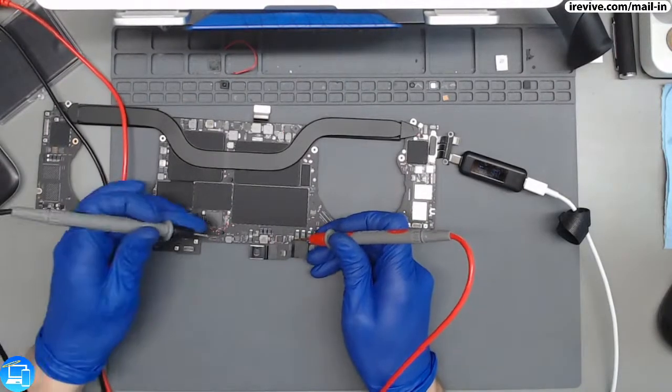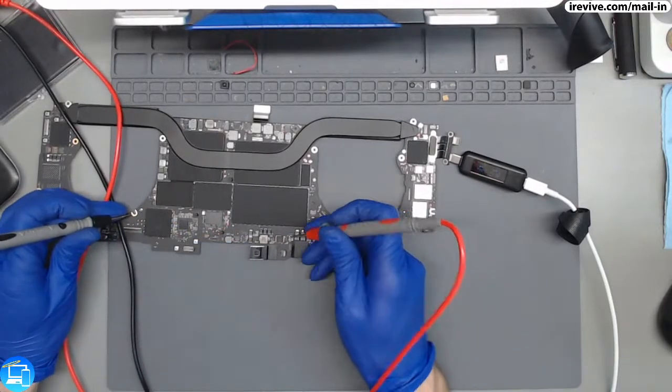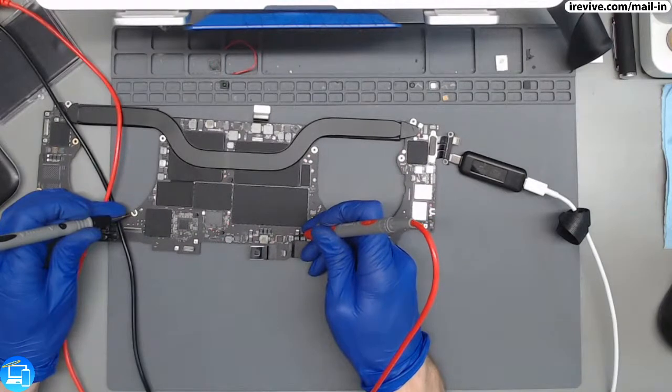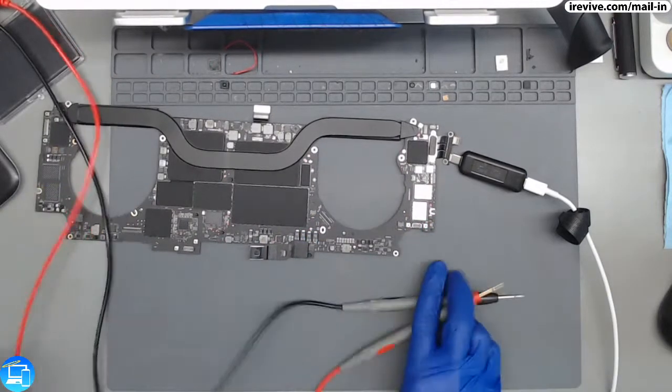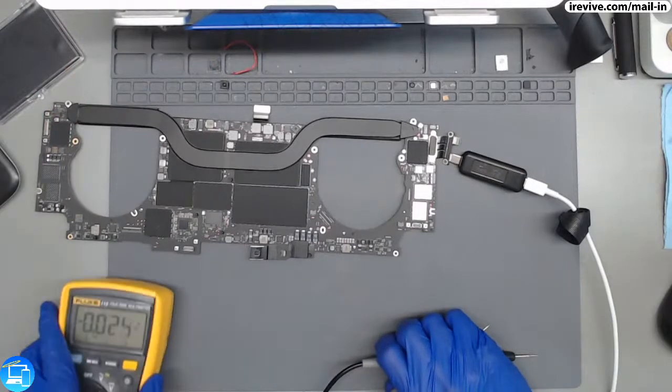Alright, so it's going to be about right here, specifically, are our fuses for our PP bus. And measuring with our multimeter, we are getting 12.61. That sounds about right for this unit. Oh yeah, I'll keep the multimeter down here.